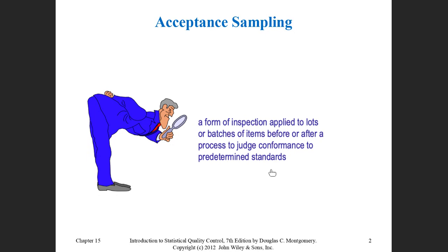If you recall, we have talked earlier about the difference between the control limits and the specification limits. It doesn't mean that if the process is having some items or sample size, there are some points out of control, they are out of the specification. Remember that the specification is wider than the control limits. Here, we talk about the samples that you examine for the specifications, not for predicting the quality or monitoring the quality level of your process.